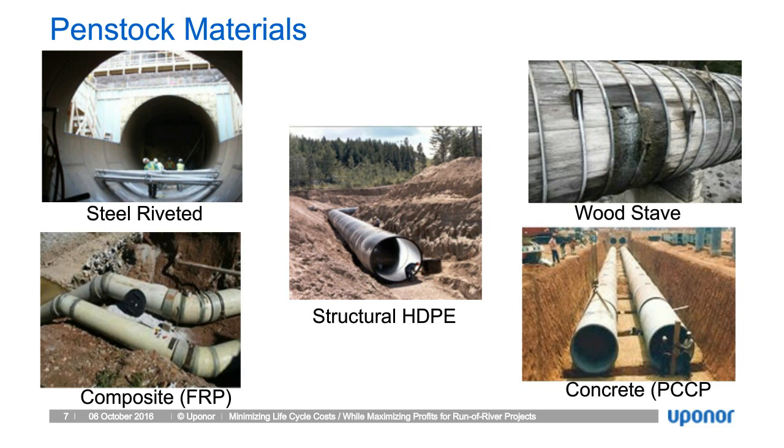It offers a good material for high pressures and comes in varying dimensions. Can be buried or above ground. Wood staves: an awful lot of run-of-river projects, which we'll be talking about today, used wood stave penstock applications. The reason for this is that a lot of the materials were local. They could get their resources from nearby forests, mill up the wood, and then locally install this.